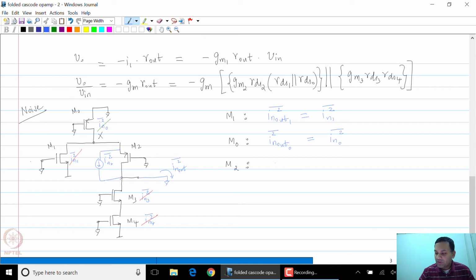So just to remind you, if you have a current source I between 2 nodes 1 and 2, as far as the rest of the network is concerned, this is exactly the same as putting two current sources in series, because the rest of the network assumes that a current I is pulled out of node 1 and pushed into node 2, and KCL is clearly valid even at the intermediate node.